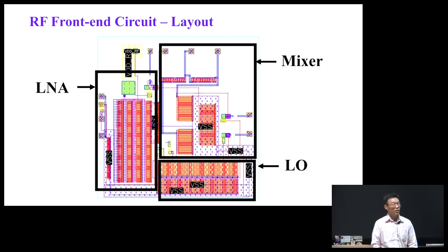With the help of the efabless script, we could put a wrapper around this entire layout so that we can integrate it into the entire chip. That script automatically connects any input and output of the RF front-end circuit to the pad. So we could go very smoothly on the integration side.